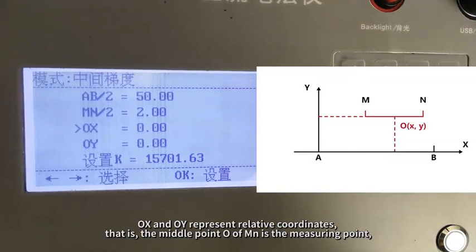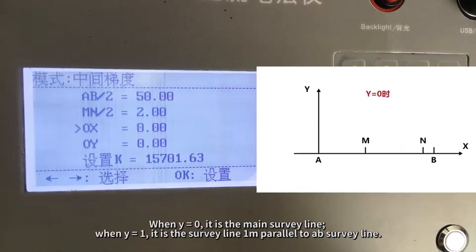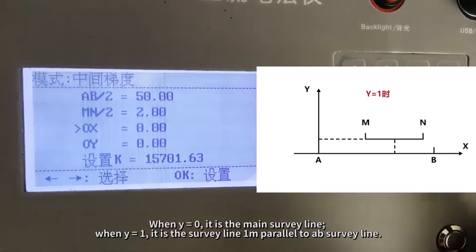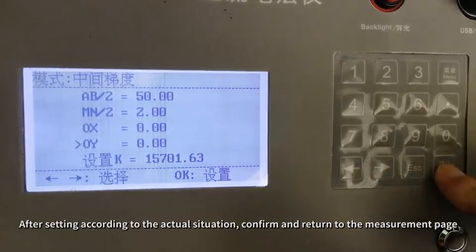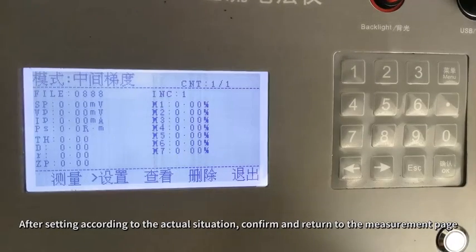O, x, and O, y, represent relative coordinates, that is, the middle point O of MN is the measuring point. AB is the x-axis of the coordinate axis, and the y-axis data is the parallel distance between MN and AB survey line. When y equals 0, it is the main survey line. When y equals 1, it is the survey line 1M parallel to AB survey line. After setting according to the actual situation, confirm and return to the measurement page.